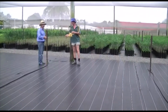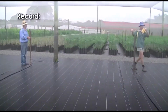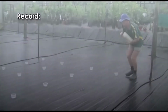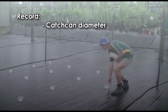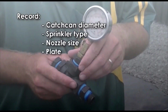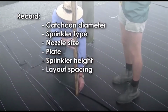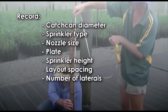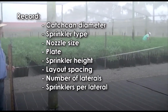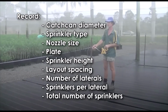Map the irrigation zone indicating the test area, all sprinkler locations and the relative sprinkler and catch can locations. Measure and record catch can diameter, sprinkler type, nozzle size, plate, sprinkler height, layout spacing, number of laterals, sprinklers per lateral, and total number of sprinklers.